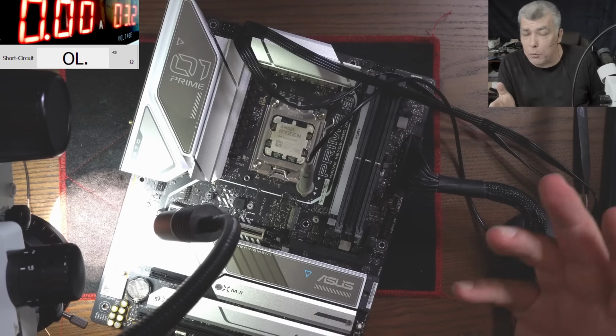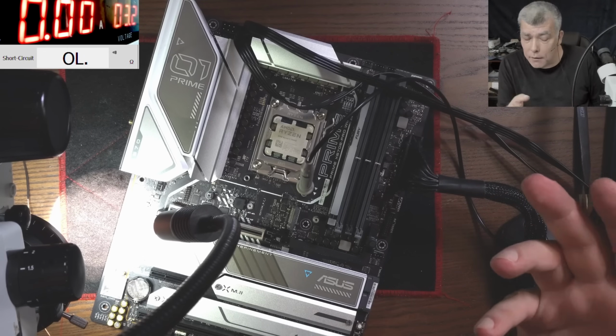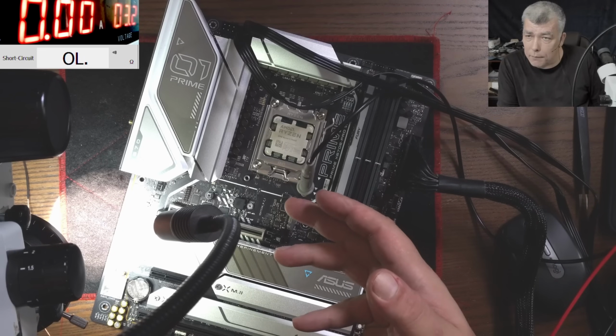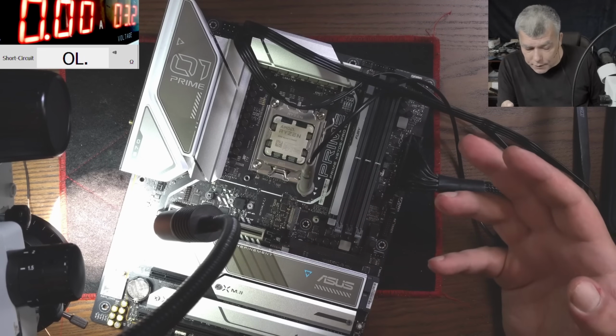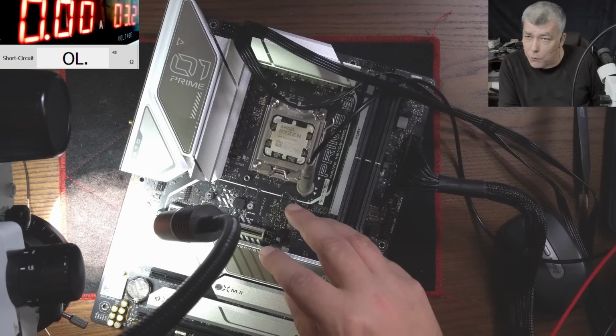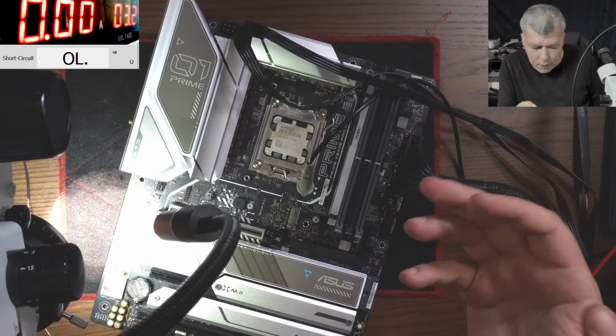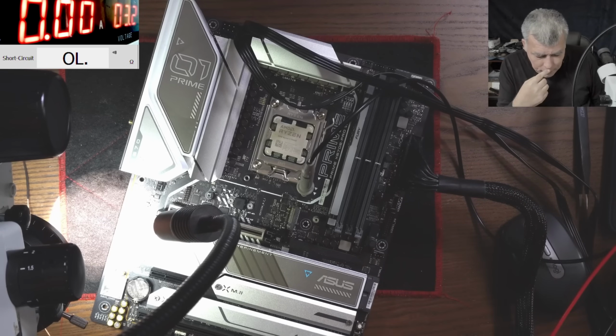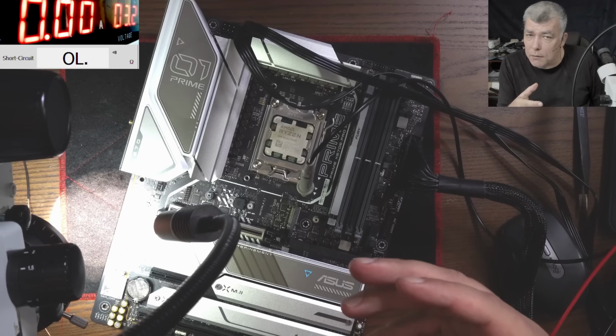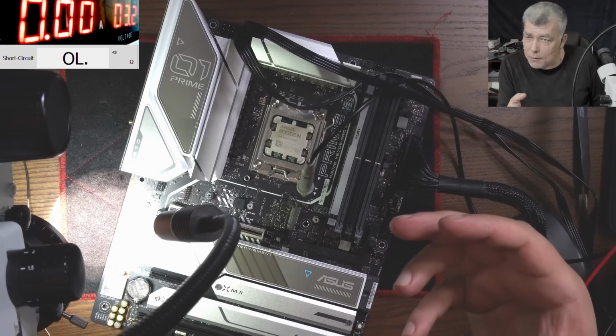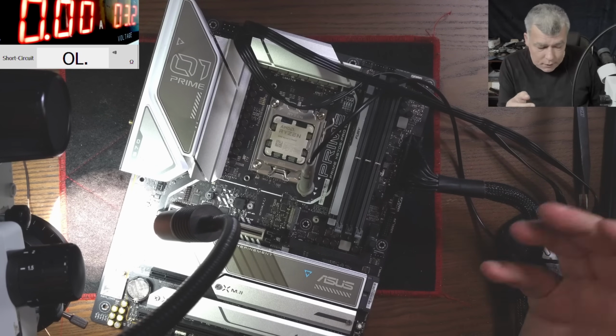But obviously, the motherboard will not be able to identify a faulty power supply. If the power supply is faulty, maybe it's shorted, but probably not, it's faulty and cannot achieve the right voltage. The manufacturer wants to not be able to start that motherboard. That's why the power good signals are there.